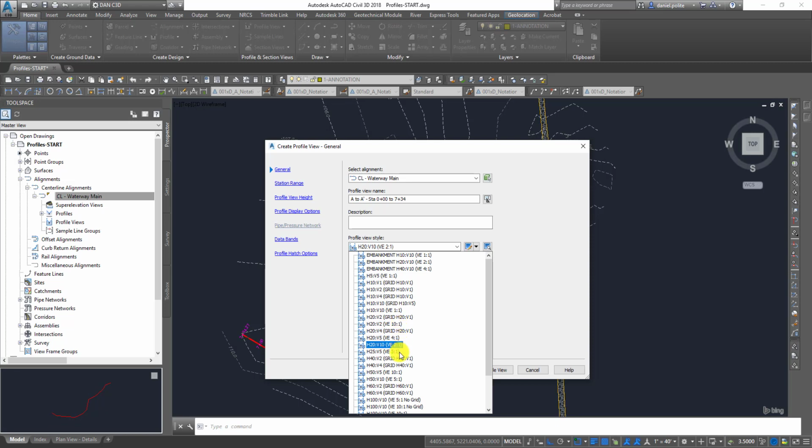Will 40 scale work? Or 10 scale work? You have to choose that. So most of the time what I do is recommend get out the engineering scale and place it right on a piece of paper and say, here's what 20 scale is going to look like if I've got to go 700 and some feet. Here's 10 scale, what I have to go at 700 some feet.